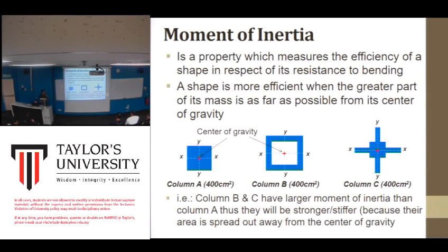But again, in terms of the formwork, it might be difficult to do, right? Because you need to have one formwork in the center, and then you have another formwork at the side. Then only you can pour concrete. Compared to this one, you only need one formwork. Maybe in terms of resistance towards bending, this is better, but in terms of cost when you construct, this one you would need more formwork.